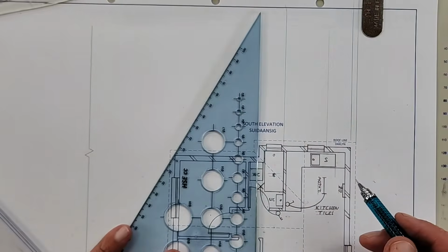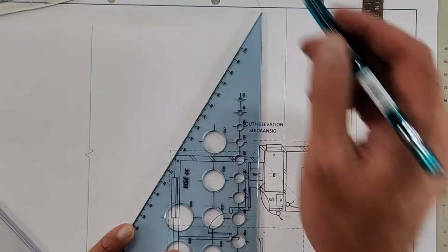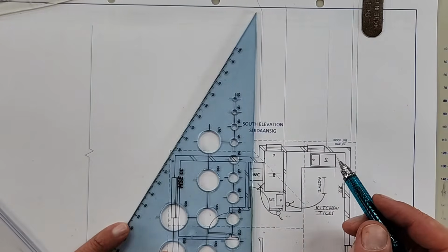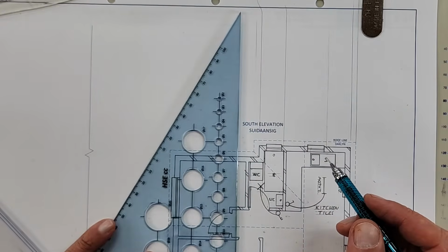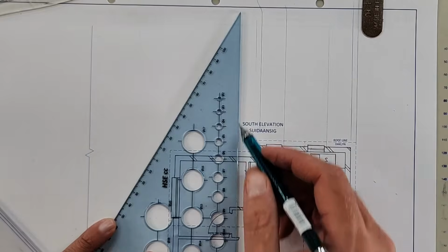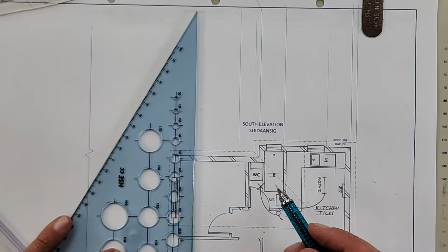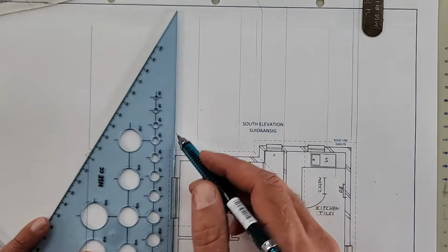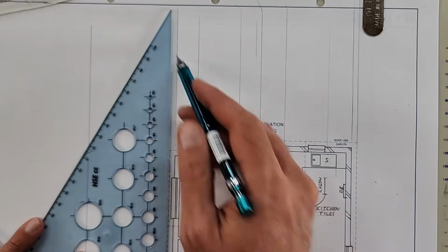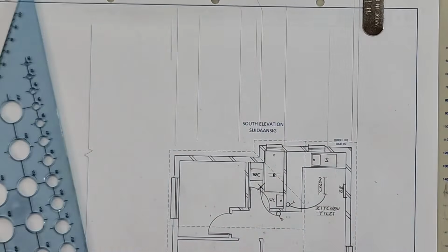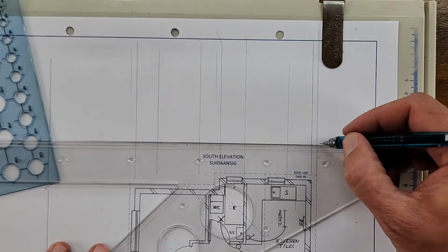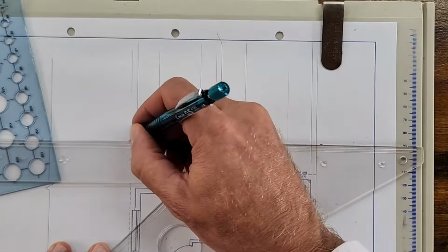frame. Then I've got a corner here. There's a roof overhang here on top, so I'll just do the line on top there. Then there's another window. Now that window, if you've drawn that, make sure you use the right lines. Okay. Another window outside, then there's the outside of the wall, and lastly there's a roof overhang, so again just on top there. Alright, then we go and we're going to start drawing this. We have a floor finish, so the first line you draw is always going to be all the way through.